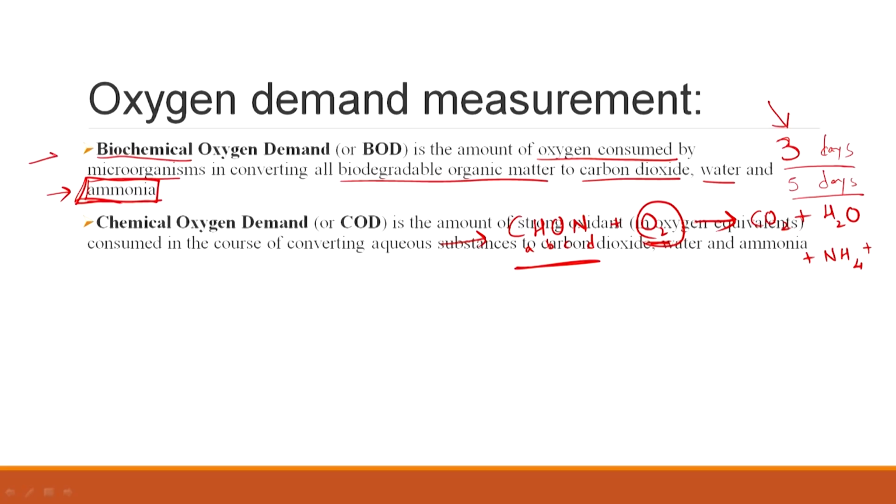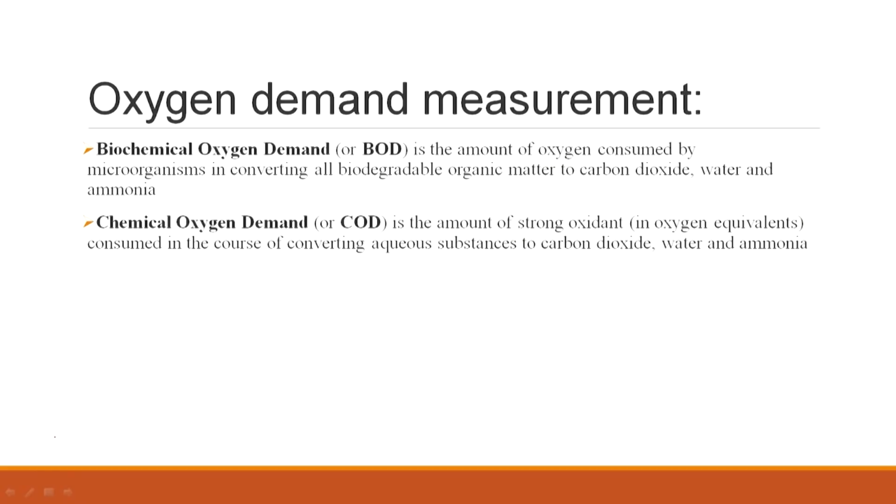That is something to understand and keep in mind, but if you do not have the time in labs or such, and you need data immediately, you can do a test within 2 or 3 hours, and it is called chemical oxygen demand. So, obviously as we can see here, we are missing the term biochemical.